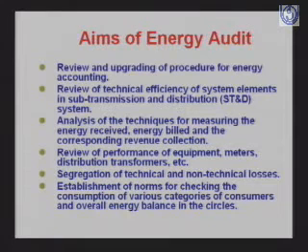So the broad aims could be review and upgrading of procedure for energy accounting. Whatever the present existing procedures are for energy accounting, whether they are successful, whether they need upgradation, whether they need updating, this energy audit would help us in that objective. Review of technical efficiency of system elements in sub-transmission and distribution systems. Audit would help us in assessing the energy performance of conductors, distribution transformers and other associated electrical systems.